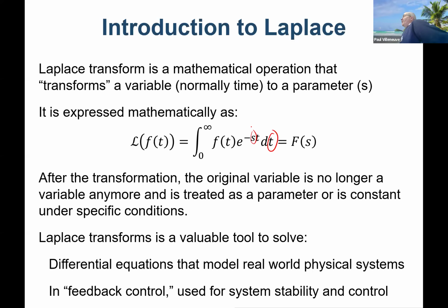You've been writing differential equations, you just don't know it. Those first order circuits that we just did, those were first order differential equations, right? We had a v of t equals e to the minus something. That was the solution to a differential equation to solve for the voltage across the capacitor. So we were writing KVL, but we were solving for it and not solving it with a differential equation. Over here, we'll use Laplace to do that.